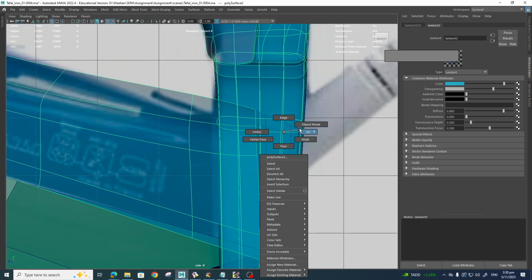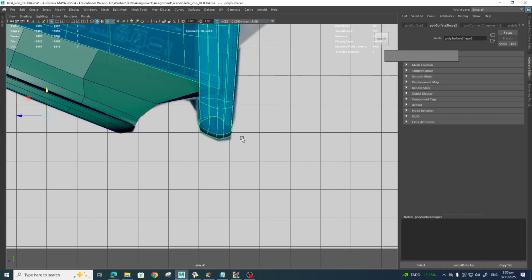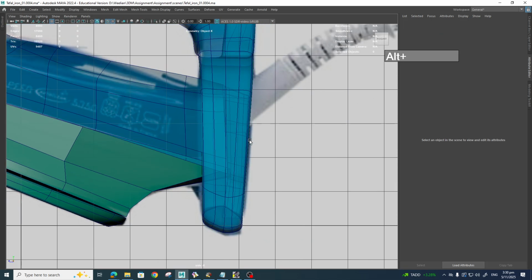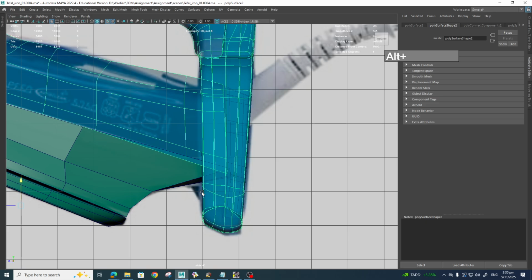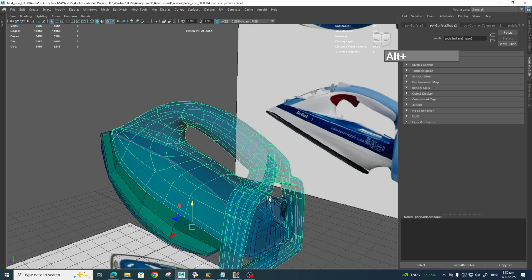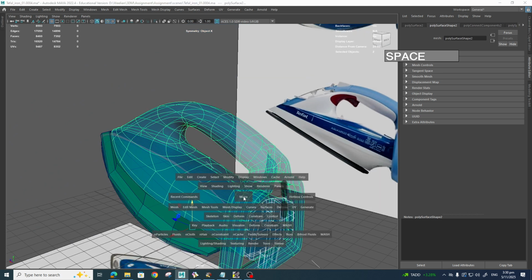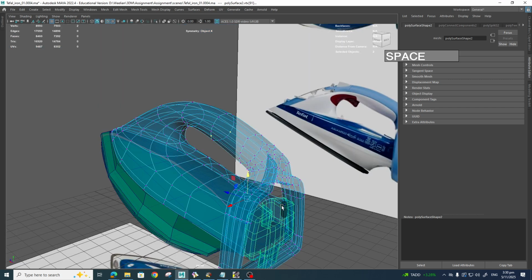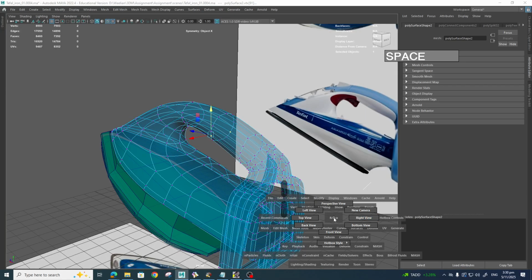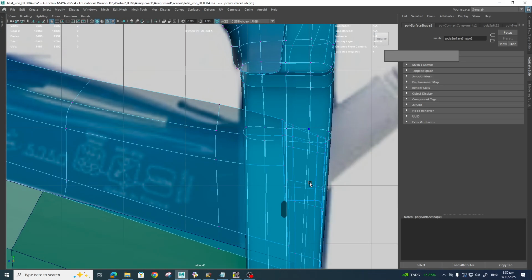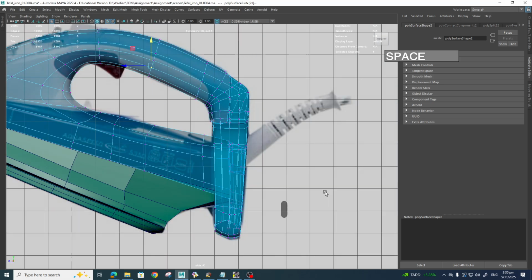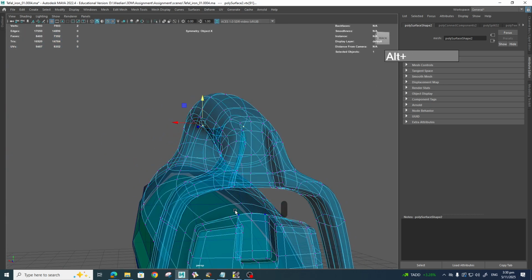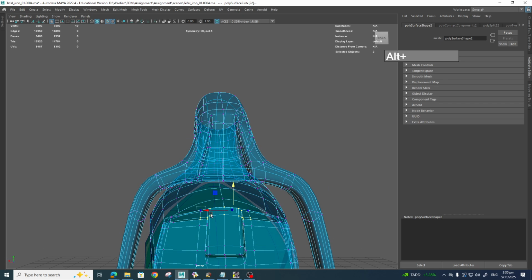And I'm going to select both objects, like this, the plug, the wire slot plug behind. Can't really select it now. Let me see what I can do. I'll select this one and hold on shift, select this one, and I can go over to vertex for both objects at the same time. This one as well, vertex selection. So one of the good things about Maya is that I can select both objects in their vertex mode. I'm going to select this group over here, this group over here. Then I turn on soft selection.